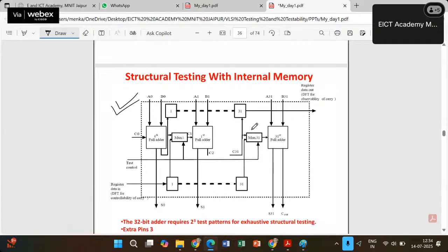So instead of passing the carry directly, the carry has been taken through the multiplexer, and the multiplexers also have a test control. With the help of this, the output of this multiplexer is either through the carry, which can be a faulty side, or through a test control. So in order to figure out whether these carry inputs or intermediate input output sets are correct or not, we can use this test control and it will be working fine in that case.